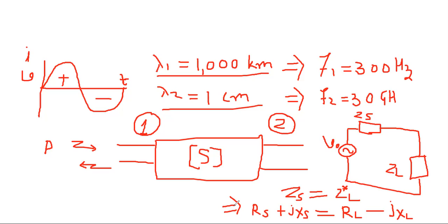So in microwave engineering, generally we are more cautious about the maximum power transfer theorem, and whatever antenna or circuit you are designing, they are tuned to each other to transfer maximum power. Suppose you design an antenna: its impedance should be matched with the source or the previous circuitry. So the input impedance of the antenna should be matched with that.